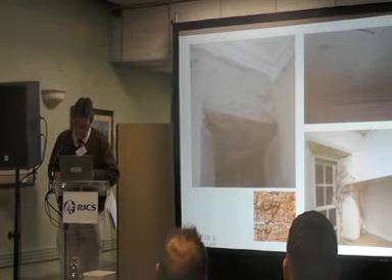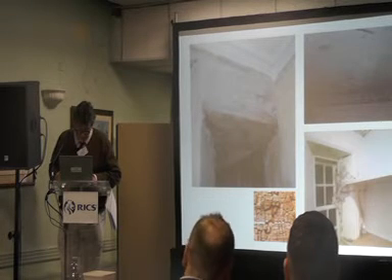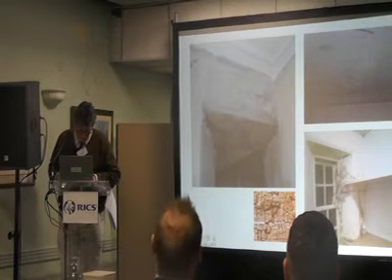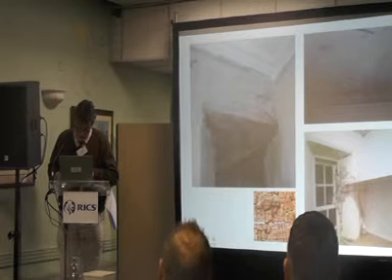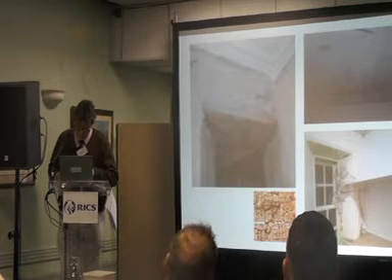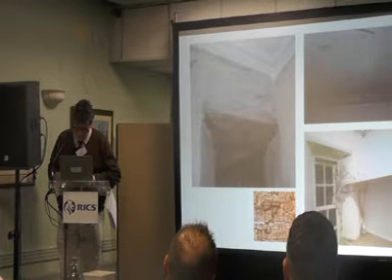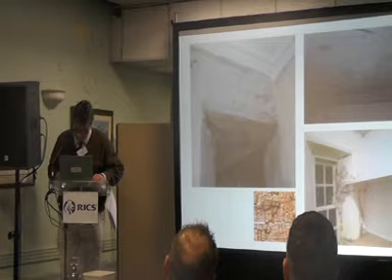And I asked the owner of the house, "How long has your son been away?" and the answer was he left before Christmas, and so the bathroom's not been used. It's a plumbing leak that's caused the problem, and it's dried up, and it's actually killed the dry rot. It's still a problem to resolve structurally, but the dry rot is dead.